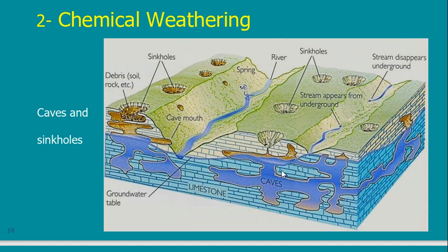But it means that in another place like this, you may have a cave. So if you go to a place and you find limestone, you have to increase your site investigation to confirm that this limestone did not reach the condition where I may have caves inside it.